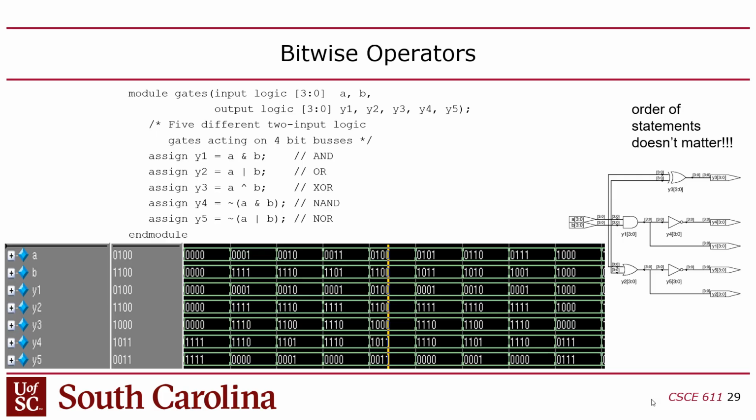So if you want to create a multi-bit signal, which is like an array of bits, you would put the brackets before the name of the variable when you declare it, right? So you would say logic, and then instead of just giving the size, and to be honest, I don't understand why they do this, you have to give it a range. So instead of saying that A and B are a 4-bit signal, you say logic [3:0]. That's meant to represent bit 3 down to bit 0.